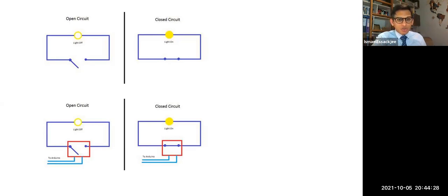Okay, you can't have a circuit switching on another circuit containing maybe 10 ampere flowing. It is going to blow off your circuit, your board and so on. So basically, this is why we are going to introduce our saver, which is, as you rightly pointed out in the chat, a relay.